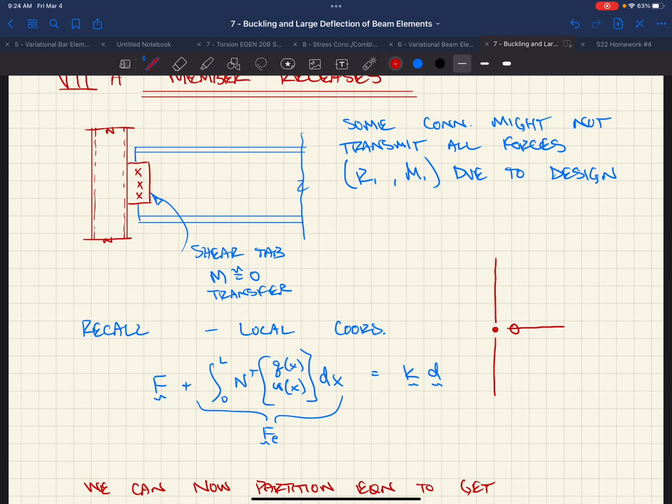A lot of times in buildings, we do what's called slip critical connections, right? You guys are probably familiar with those, right? Whether in Damon's class or in practice, right? We're essentially squeezing the connection so hard that there's enough normal force and a mu, a friction coefficient, that we're going to be able to transmit a lot of force even if we didn't even have bolts in it, right?